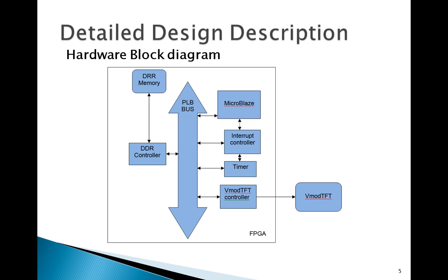Here you see the block diagram of the hardware. You can see the MicroBlaze microprocessor, which is connected through the PLB bus to the other controllers, like the DDR controller, interrupt controller, and the VmodTFT controller. Here we have the timer. Here we have the DDR memory, and this is the VmodTFT module.